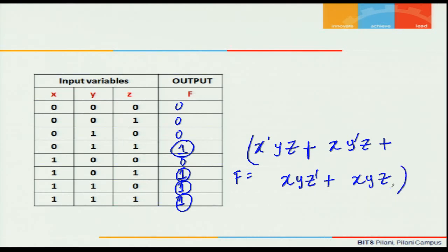We could convert this into a logic circuit using gates. We could do an AND OR implementation or a NAND NAND implementation. So, we will have the first level AND gates followed by the second level OR gates, which is becoming an AND OR implementation. We could also make both levels as NAND gates, that will become a NAND NAND implementation.